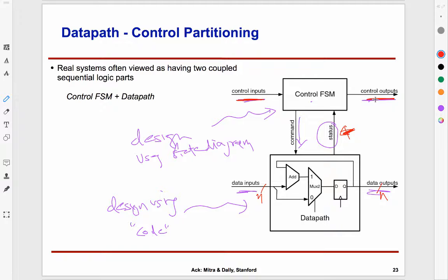What your design, the circuit, will have to do is look at these wires, and whenever it sees something went low, it has to keep sampling it until it sees that it went back up again, because the key press itself may take, as I made the case, millions of clock cycles. So real FSMs have to deal with the issue that the timing of the outside world may be very different than the timing of your internal thing. Your clock speed can be very high. These signals coming from the outside world, physical, mechanical signals, may change very slowly, and you'll have to design your state machine to account for that.